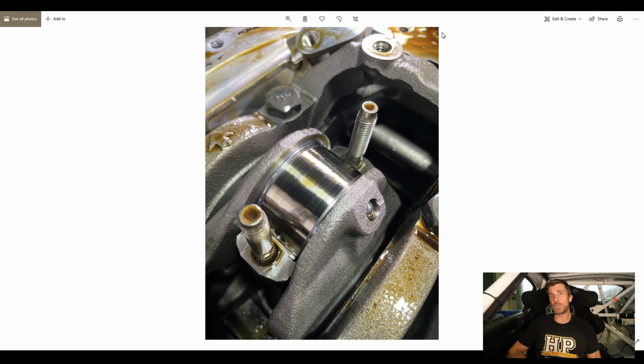We will also be using a torque plate during the honing process. We're using an ARP Custom Age 625 Plus stud in the factory 11mm. That provides a lot more clamping load than the stock head bolts, and what this can do is distort the bores slightly when they are torqued up. So we want to torque plate hone the engine block, and that way we're replicating that same distortion when the studs are tight. So theoretically what this means is when the head is bolted on in place, we're going to have perfectly round bores, which allows our rings to do a better job of bedding in.